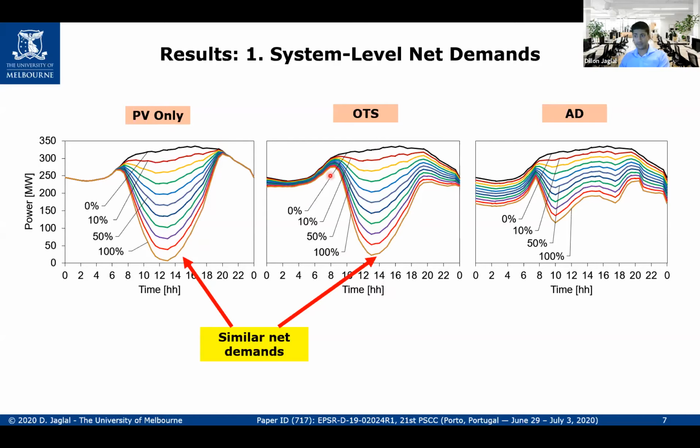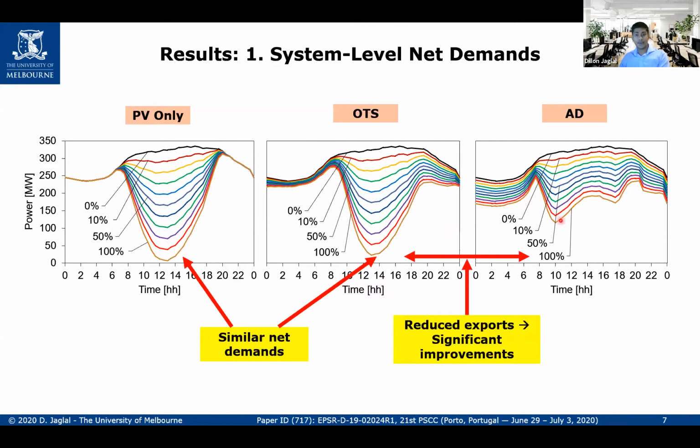And then for AD, the operation is to reduce the peak exports from PV, and again, aim at distribution networks. So by reducing that peak export from the PV on a large scale from all the customers, it's being reflected here. And we have a much flatter behaving profile. My colleagues call this, instead of calling it the duck curve, the platypus curve, because we have a platypus here and it kind of looks a bit like it. It's a bit funny.